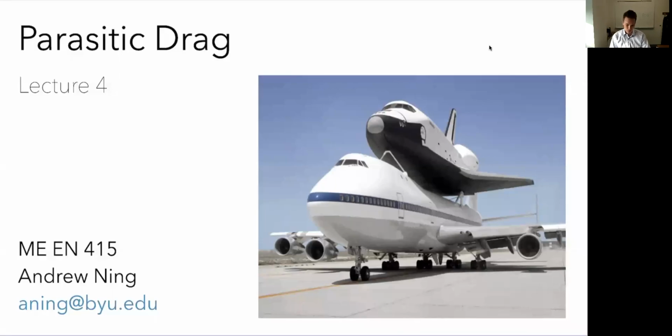Today we're going to talk about parasitic drag. As we introduced in class, parasitic drag is the combination of both skin friction drag and pressure drag. Remember, skin friction drag is that drag from the shear stresses, whereas pressure drag is from the pressure. Okay, in class we also talked a bit about laminar versus turbulent boundary layers.